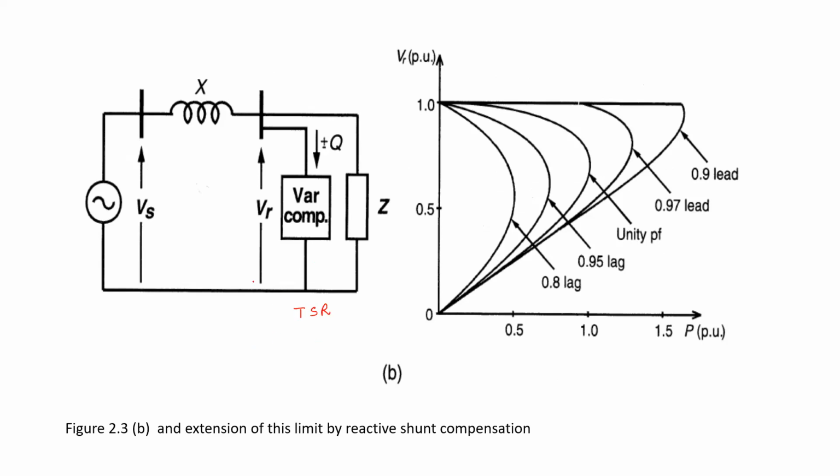Or simply, for our simplicity or for understanding purposes, we can see the APFC, automatic power factor controller, where the power factor of the load remains near unity by setting the value in the reactive power manager. And there are a number of capacitors.